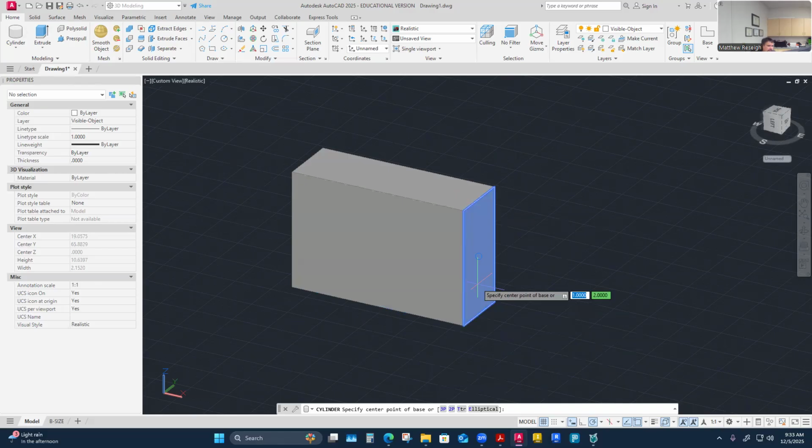If you reference this plane and you lock in on that vertex, what you'll notice is it's going to draw the circle in relation to that plane. It kind of uses that reference. If you pause on it, it's going to use that as your reference plane. Same way if I was here in the cylinder command and I came in here and hit this surface first to this point, it's going to try to draw that way. So this can be a little bit annoying.